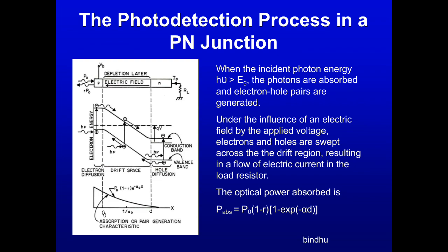So what is the principle lying behind this photodetection? Photodetector uses a principle of input as a photon energy, optical light. The output is electrical. So all our electronic components which work on electrical energy cannot directly function on an optical input. So we have these photodetectors to be installed in the receiver segment of a fiber optic communication system. This photodetector is capable of converting photon light energy into electrical energy.